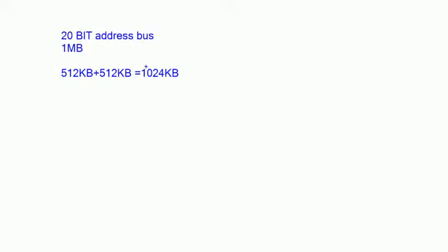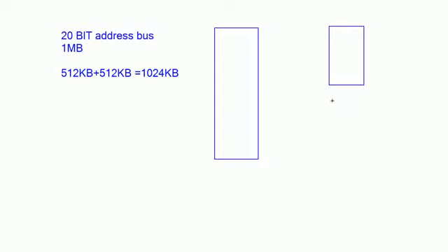Okay. So here I'm assuming that I'm designing a microprocessor based system, and I would like to interface the memory device. This is the other way of explanation. What is the maximum memory that can be accessed by our 8086 microprocessor? It is 1 MB. But unfortunately, I'm assuming that in the market we do not have 1 MB memory devices. We have only the 512 KB memory devices.